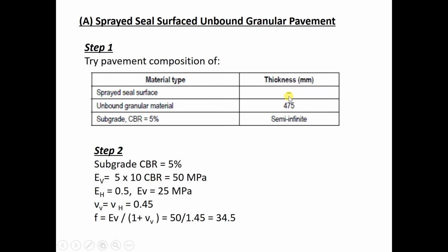If your design standard axle repetitions for any of the three types of distress is greater than the allowable, then the pavement will fail. So it's supposed to be less than the allowable. Okay, so we just go through this.